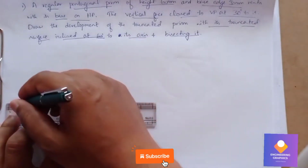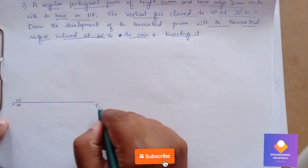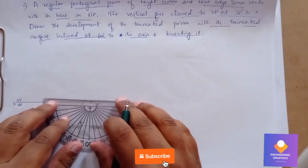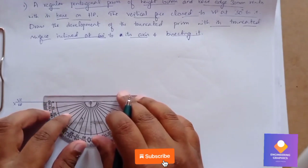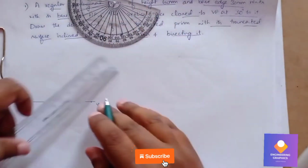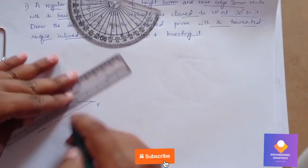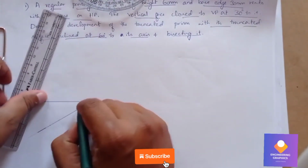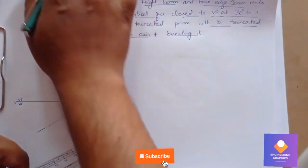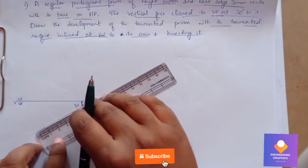So first I am going to draw an XY line, writing VP, HP and Y. Here we need to construct a pentagon by considering a 30 degree angle line. With respect to that 30 degree line, we need to place our pentagonal prism. So take a reference point, mark 30 degrees and draw an angle line. Mention angle 30 degrees. Here, with respect to VP, close to VP and inclined at 30 degrees. Now we have to consider the edge of 30 mm.